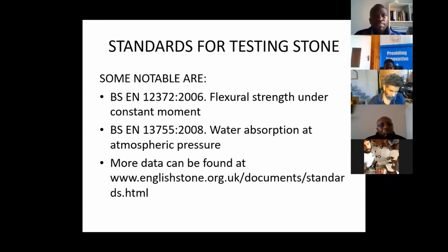There are also some standards for testing stone material. Notably, there's BS EN 12372 of 2006, that's for flexural strength under constant moment. There's one on water absorption at atmospheric pressure. And more data on the tests and standards that are applicable can be found at englishstone.org.uk/document-standards.html.